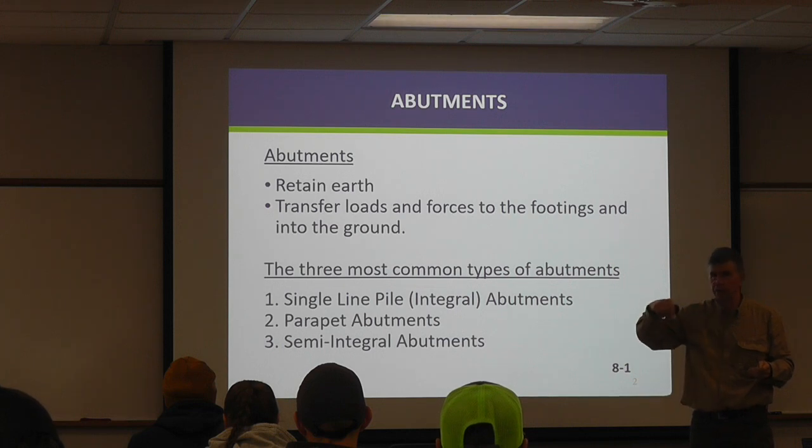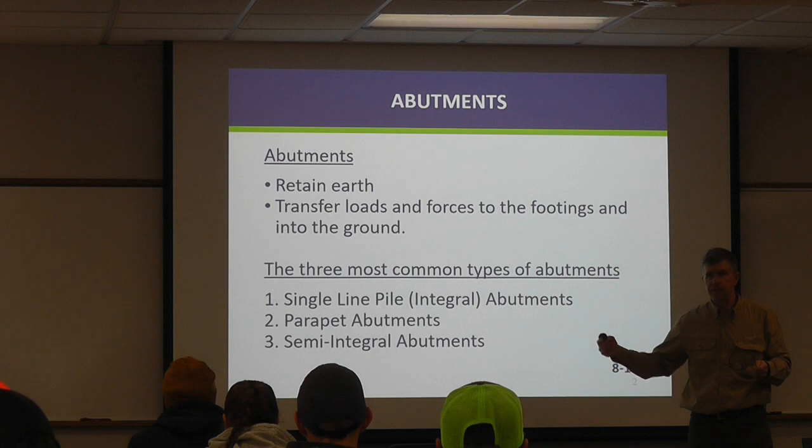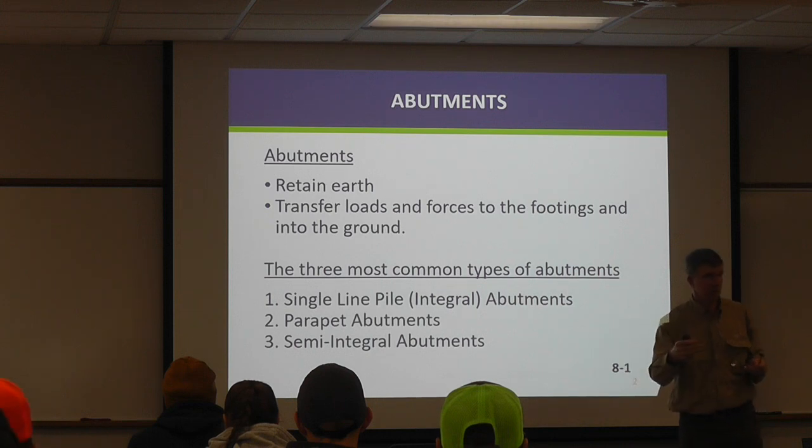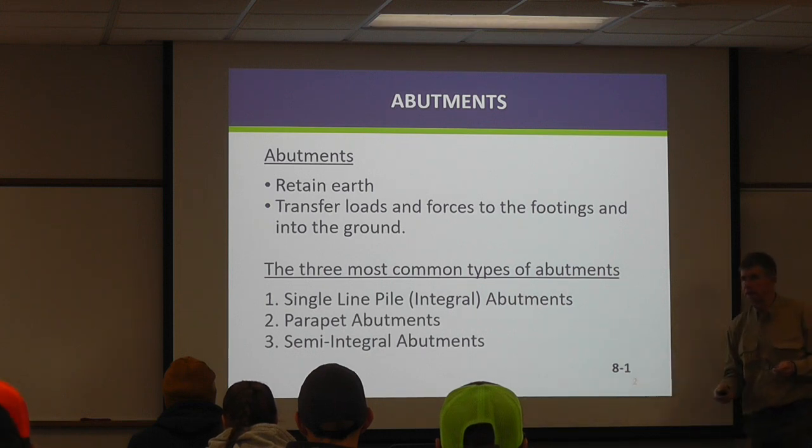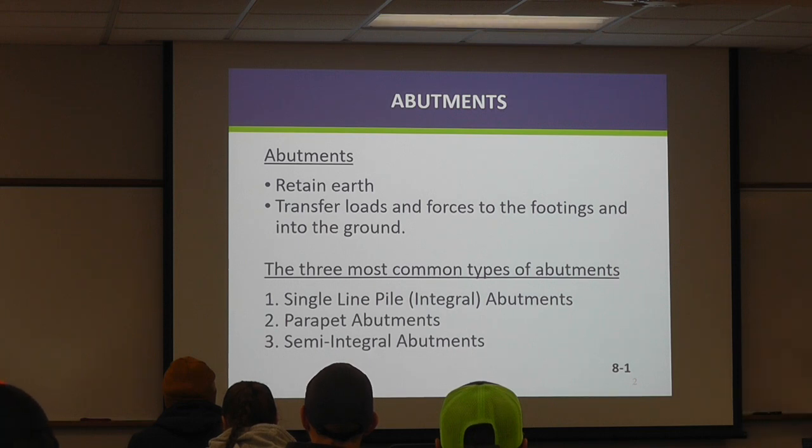So that's a vertical load that comes through the abutment. We also have, on the back side of the abutment, horizontal soil pressures that are pushing against the abutment, so it experiences those kinds of loads. And so the abutment is transferring loads and forces into the footings and into the ground.